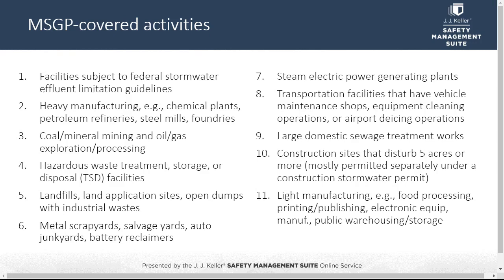Now you can imagine that rainwater and snowmelt could potentially pick up pollutants at these locations, so these are specifically regulated by the multi-sector general permit. Now I should also mention that you will want to check Appendix B, as in David, of the permit to verify that your industry is covered. The permit is limited to discharges from standard industrial codes or SIC codes listed in Appendix B.